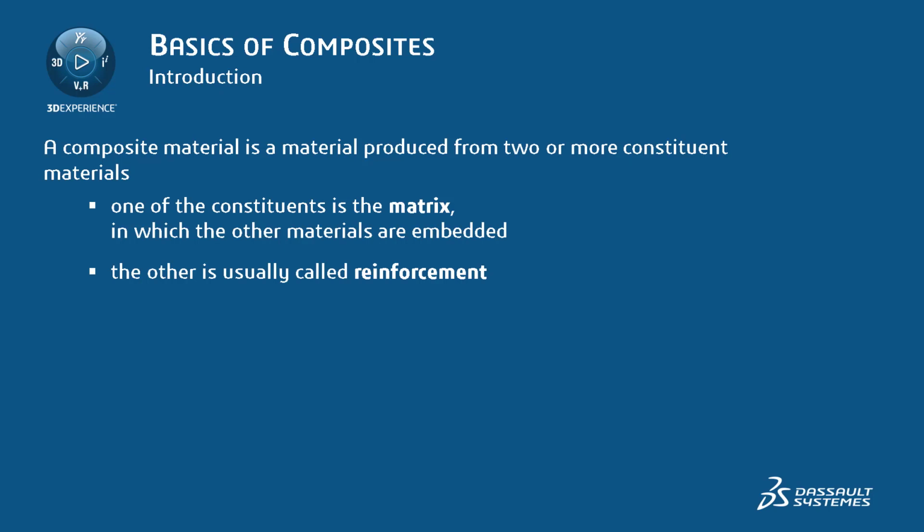The main role of fiber reinforcement is to provide strength and stiffness. Fibers on their own are poor under compression, but great under tension. The fibers are packed tightly together and encased in a resin. A well-known example of composites material is carbon fiber composite. In such an example, the reinforcing fiber is made from carbon, which is strong and stiff, and epoxy, a plastic resin that holds the fibers together. Another example would be a polyester resin reinforced with a glass fiber, GFRP glass fiber reinforced plastic or fiberglass.